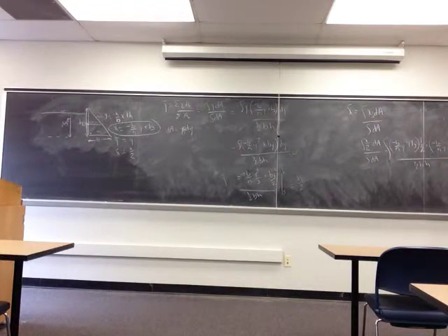So I skipped a couple steps in here. You've got to multiply these component parentheticals together, and then integrate it. And this is what you'll end up with: b squared over h cubed times y cubed over 3 minus 2 times b squared over h times y squared over 2 plus b squared times y. And evaluate that from 0 to h, and lo and behold, the x component of the centroid is b over 3.